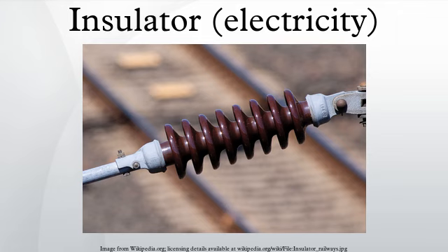Some wires have a mechanical covering with no voltage rating, for example service drop, welding, doorbell, thermostat wire. An insulated wire or cable has a voltage rating and a maximum conductor temperature rating. It may not have an ampacity rating, since this is dependent upon the surrounding environment.